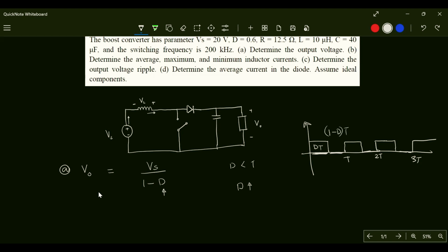So this is the time period when it's off. This is the off period, right? This is the on period, isn't it? Remember that I said duty cycle is the time when the waveform is on divided by the total time period. That's duty cycle. So you can see that this one is almost 50-50, right? So 50% on, 50% off.